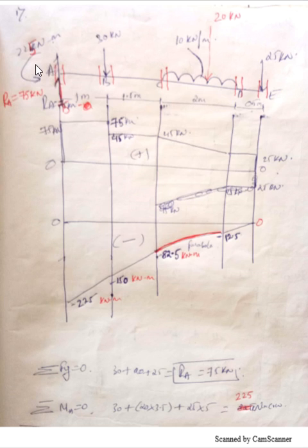This will be the last problem for shear force and bending moment diagrams, wherein again I have considered a cantilever beam, but there is also a UDL acting on this beam. Okay, the same thing we need to follow. That is, first I need to find the reaction force at the cantilever beam. There is a vertical reaction force and also a reaction moment.